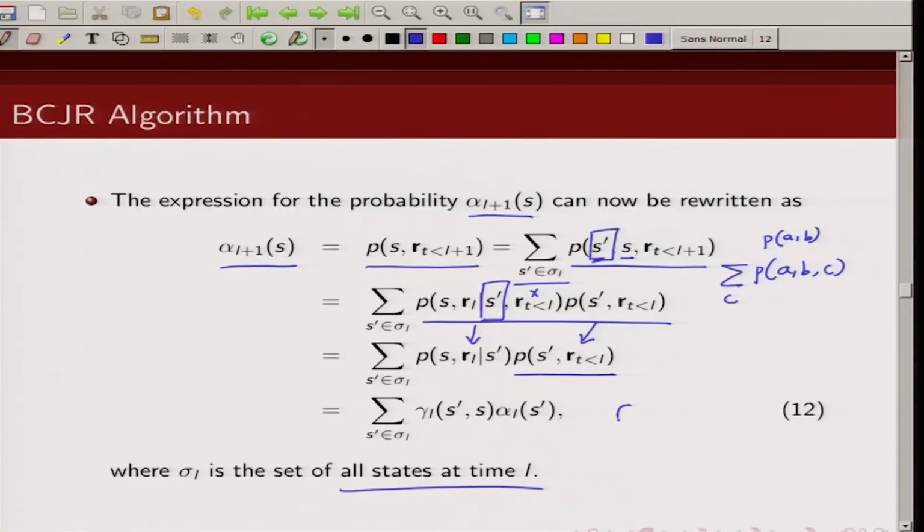Let us go back to our 2 state code example. So, this is the 2 state code, this is my all 0 state, this is state 1. There are 2 transitions here: input 0 output 0 0, input 1 output 1 1, here input 1 output 1 0, and here input 0 and output 0 1.